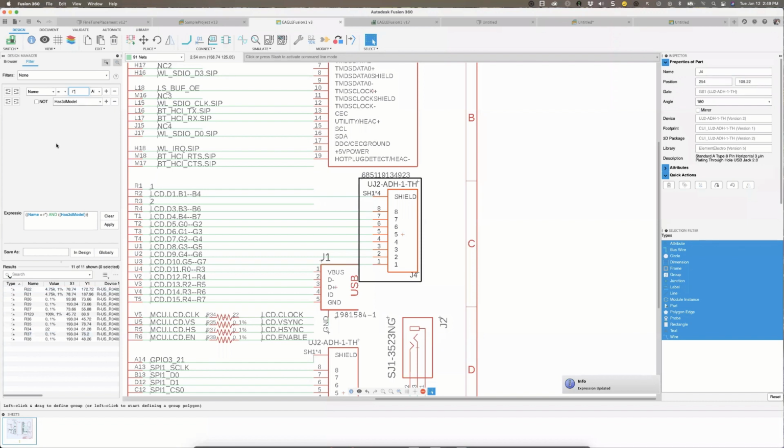If they don't have a 3D model, which is the case where I think you would use it, that's where I've used it the most. If there's not a 3D model assigned to it, I'll select here, and it will give me a list of all the components that do not have 3D models. That way I know I have to go back and edit those parts. That way I could add 3D models to them as well. Okay. So this is very useful.